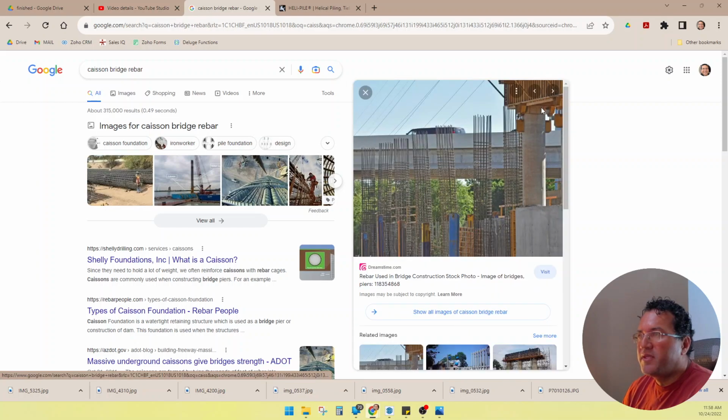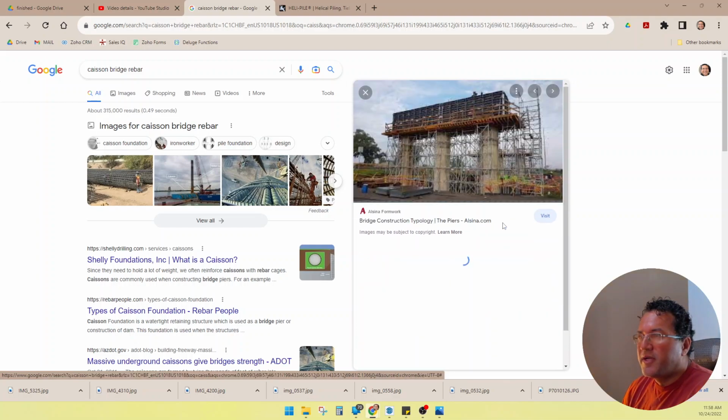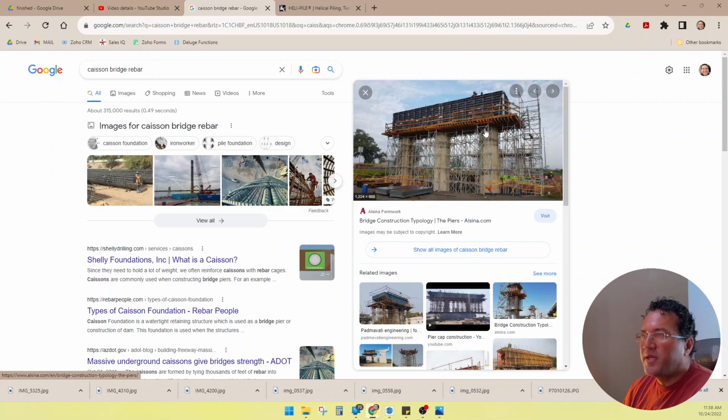You can see the caisson here. You can have the caisson below grade. You can have it above grade. And you can see here they're actually building a grade beam on top. So it's typically a much bigger job when you're doing caissons. Of course, looks like a big highway job. Whenever we're designing them, typically our grade beam is still pretty small. We're not doing giant caissons like this, but they can become a bit expensive.